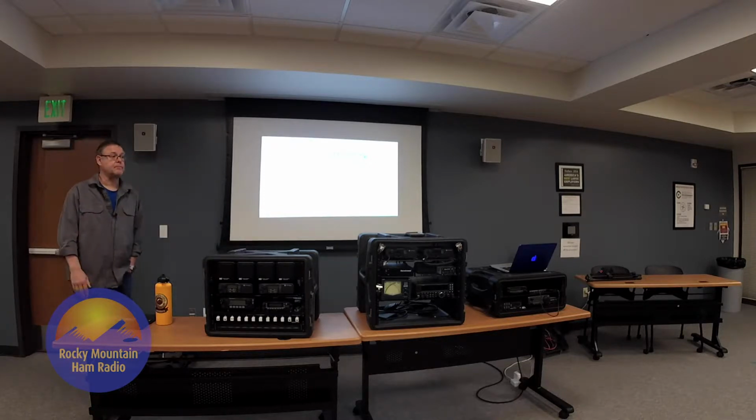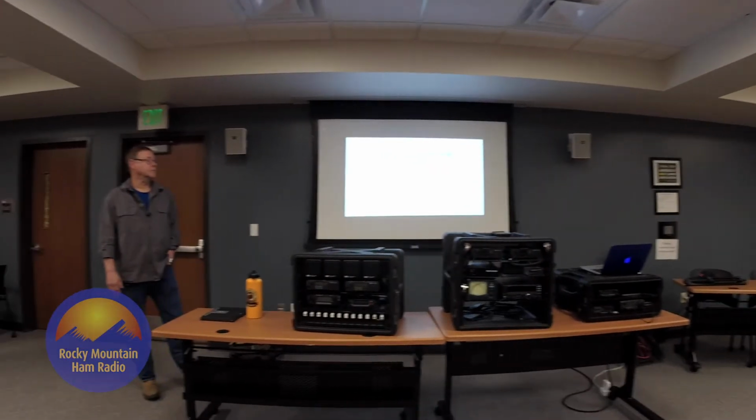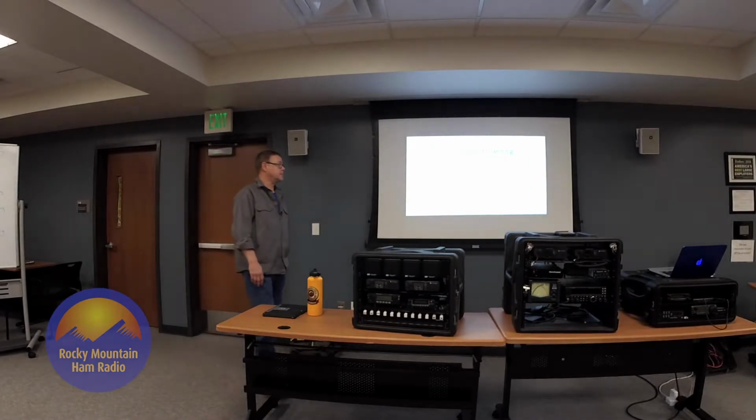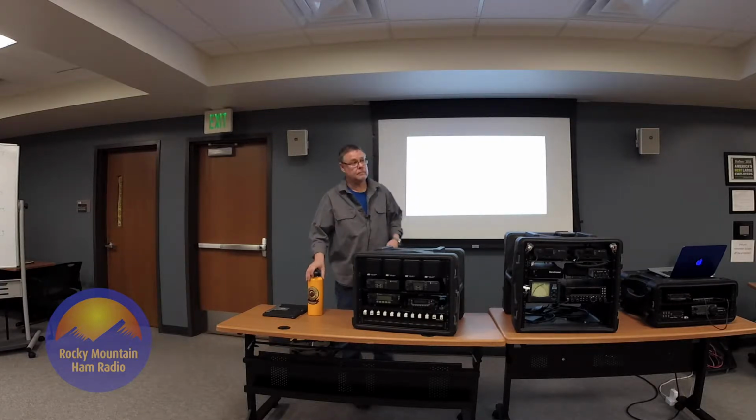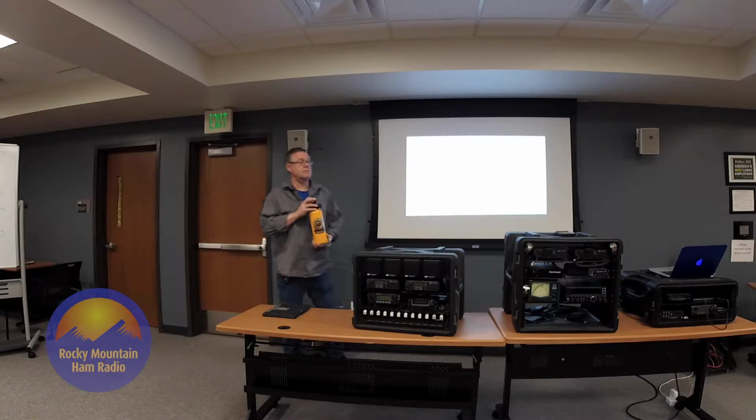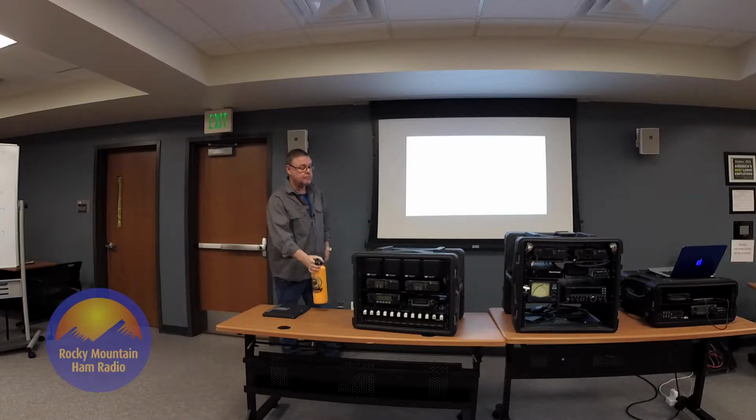Yeah. We have two of them that have SLR 5700 repeaters in them, which is a 1U repeater and then a duplexer. And that repeater running 50 watts into that box on DMR with a really good duty cycle, that box will get 150 degrees in no time. You don't want to close it in.